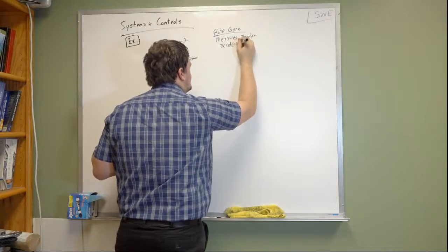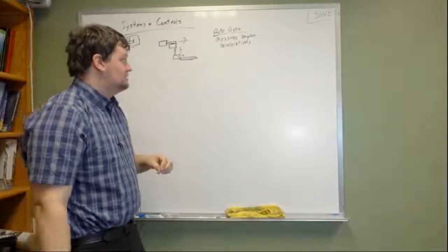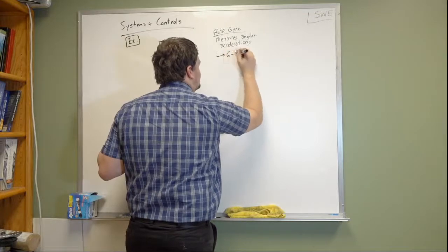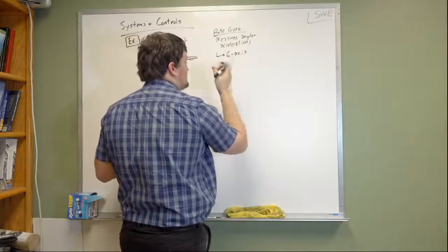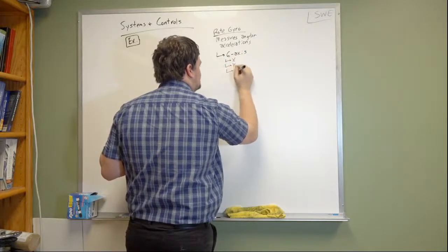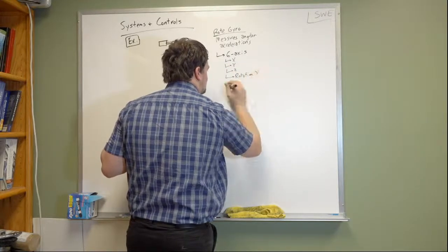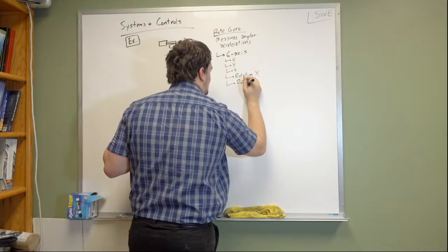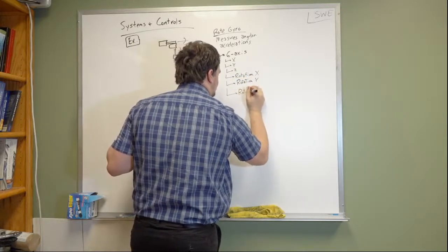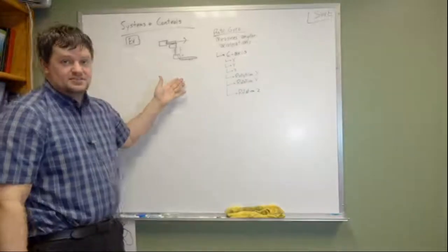And if you get a 6-axis rate gyro accelerometer, what that basically means is that it measures accelerations in X, Y, Z, rotation about X, rotation about Y, and rotation about Z. Okay, so a rate gyro, if you put it on here, has the ability to measure all of these.